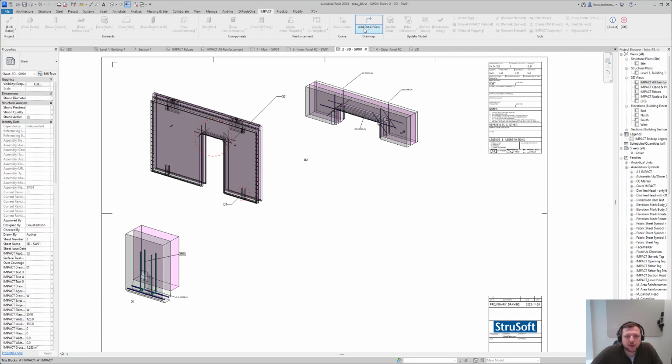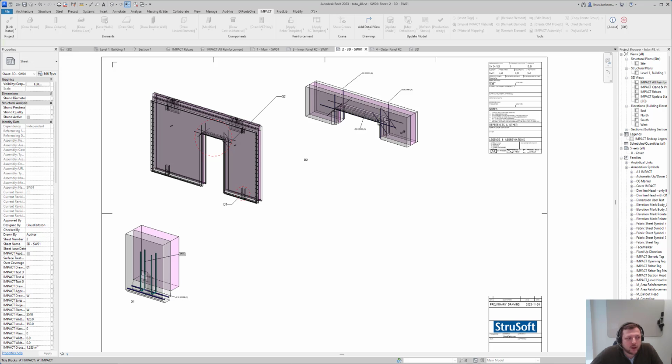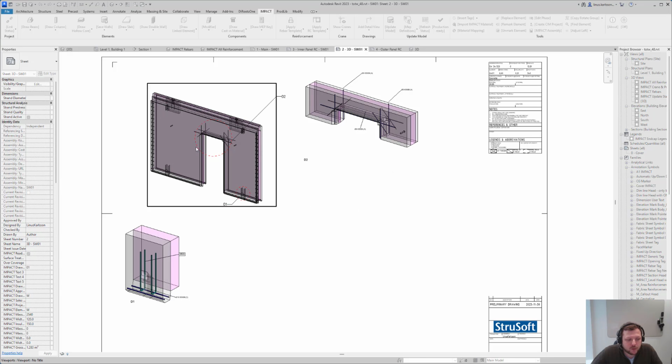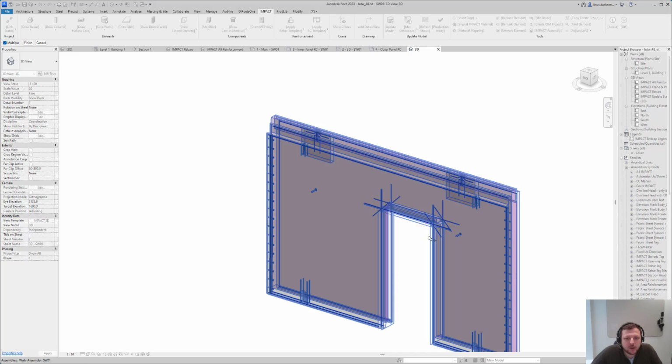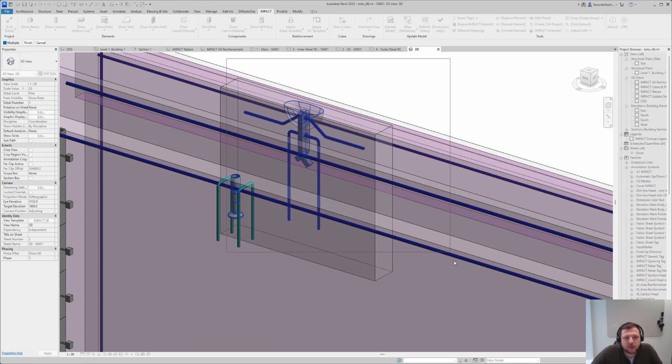It's very easy. We go here to the shop drawing options and say add detail view, and we get this dialog popping up. We need to name the detail, so D3 in my case. I'll select components, and first I need to select the main view and then zoom in here. You can select by dragging, and then we take the selection and make a bounding box around it.